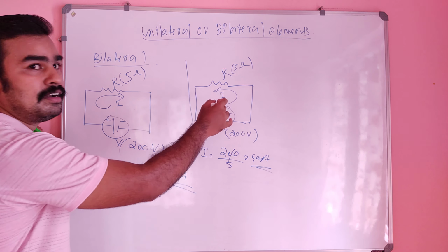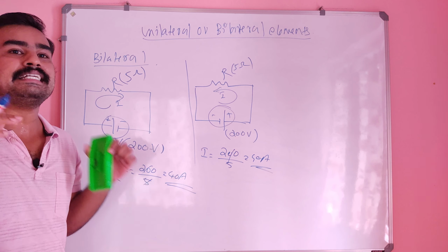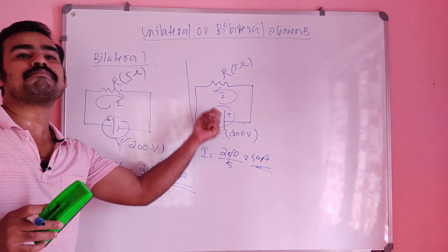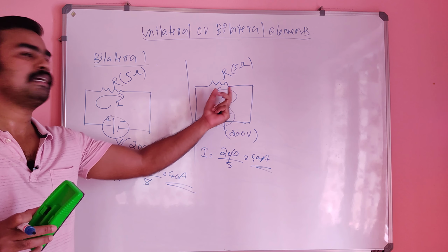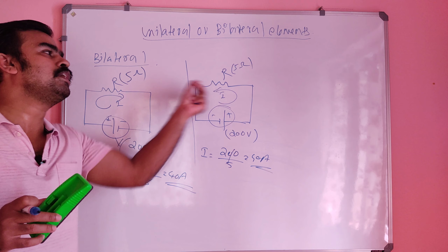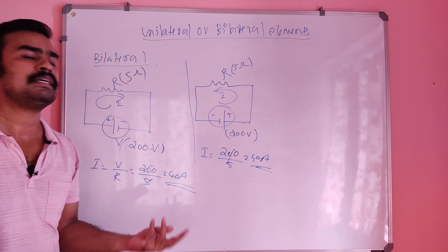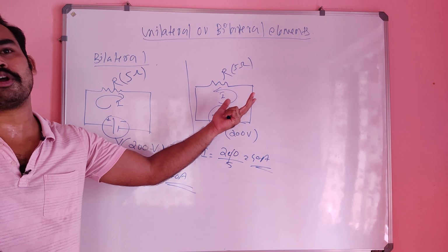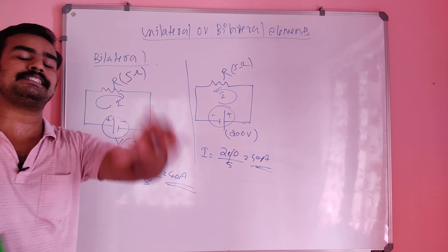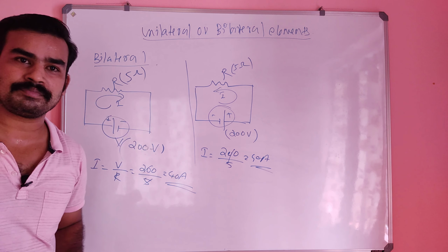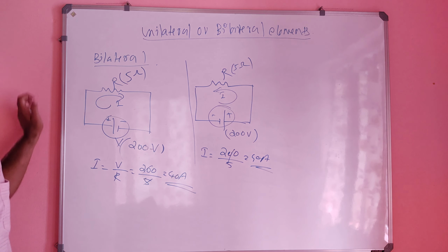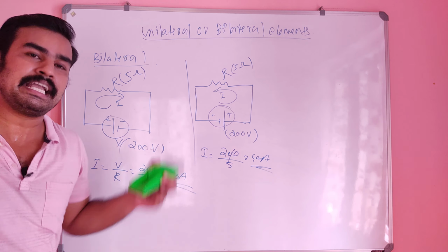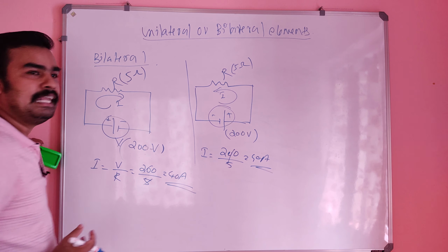The direction of current in that element doesn't affect its property. Its property is, suppose, generating heat; you assume generation of heat is the property of a resistor. It won't affect the property of the element, which is called bilateral. That means in either direction it behaves the same. So that is called the bilateral element.